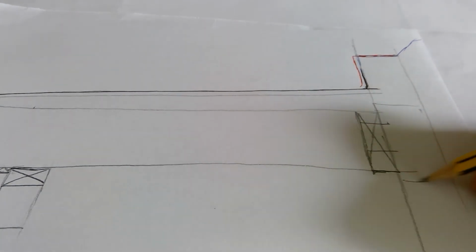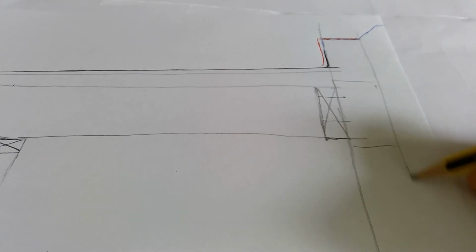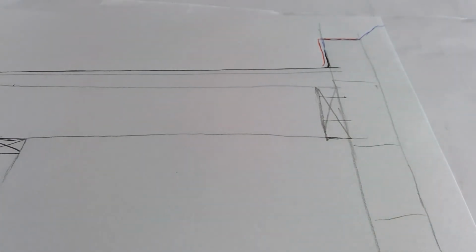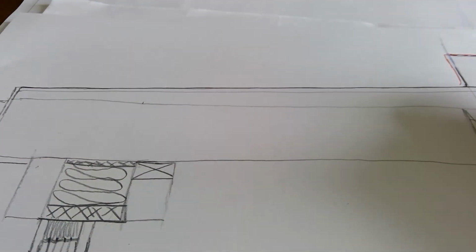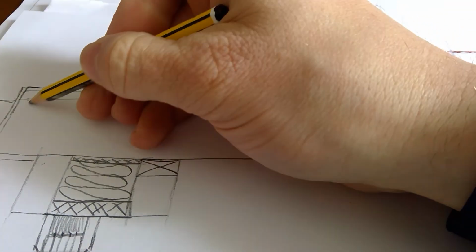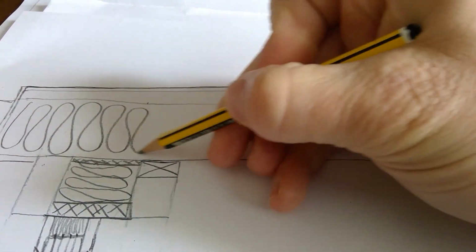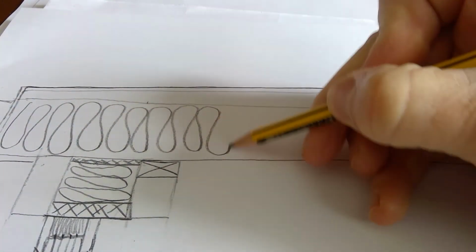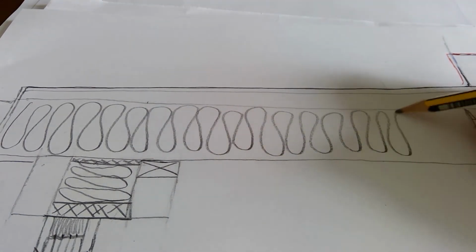You can draw on a few blocks there. It doesn't say how far to go down here with the wall, so maybe just go another block or two down further and you'll be fine. It says it's an insulated roof, and as we said, the felt rests on top of the plywood, so we can't put our insulation between those because the question says that's resting on there. So we'll put our insulation in between the joists. We'll run that all the way along there neatly, all the way to the end.